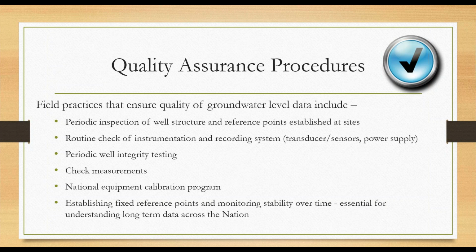If your site is involved in routine data collection, you have to do well integrity testing to make sure that the well is still in connection with the aquifer. Also, establishing fixed reference points and monitoring the stability of those reference points over time is essential for understanding the long-term data across the nation.